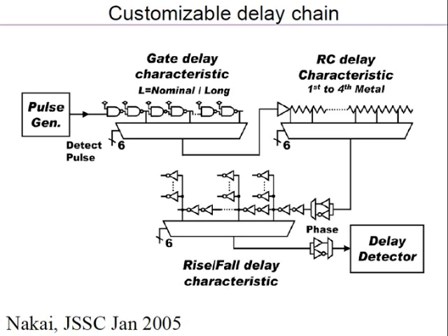Secondly, the critical path itself could be very complex, in the sense that the actual path might have a lot of fan out and so on. So it may not be that easy to replicate the same thing. Because the critical path has a spatial structure, the signals are going and wire is spreading out and so on. Replicating the same thing might just take too much area, and you will not be able to properly replicate it because of that.